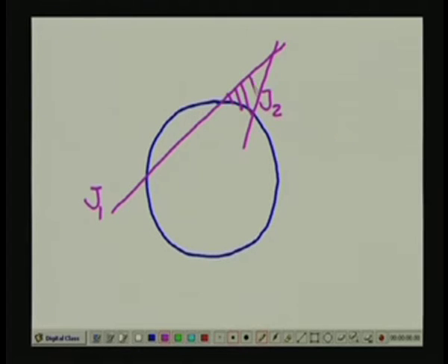Then you cannot always say whether this particular wedge is going to be susceptible to falling over into the tunnel opening, because of the frictional strength of the bottom surface of the joint and the strength because of dilatancy near the top surface of the joint.